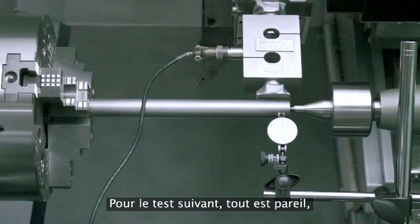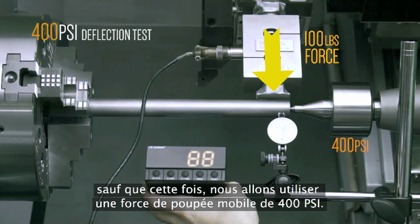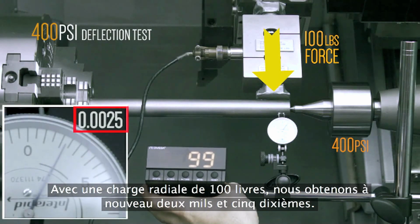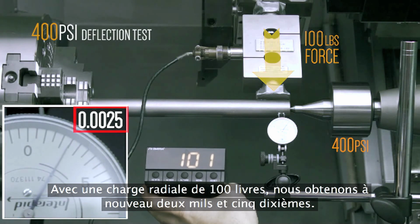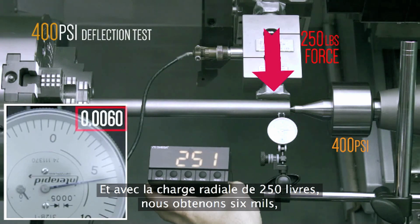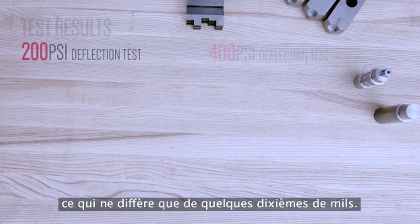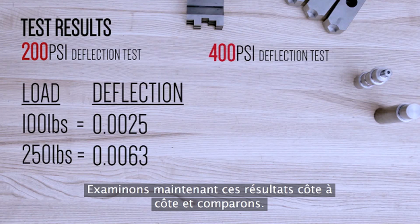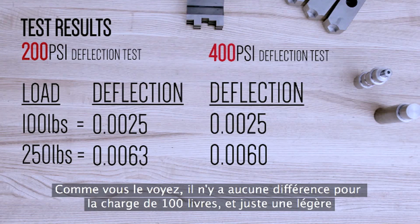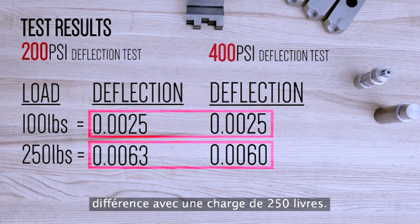For the next test, everything's the same, except this time we're going to use a tailstock force of 400 psi. At the 100 pound radial load, we get 2 thou 5/10 again. And at the 250 pound radial load, we get 6 thou, which is only a few tenths different. Let's take a look at these results side by side and compare. As you can see, there's no difference for the 100 pound load and just a slight difference at 250 pounds.